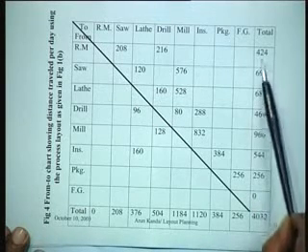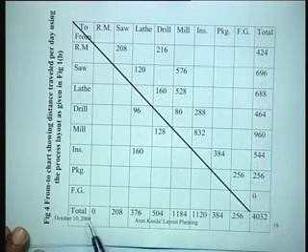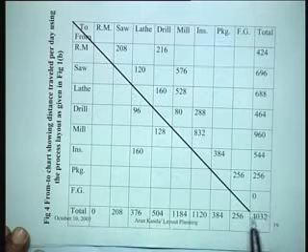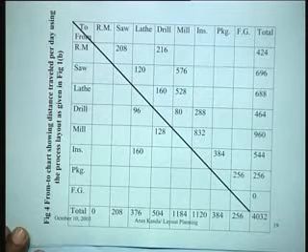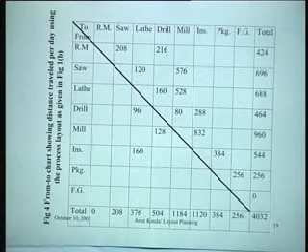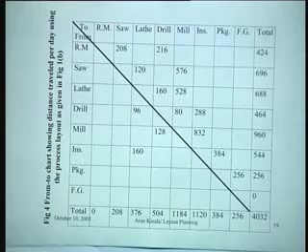If you sum up these values, this column or this row, the total value is 4032. So it shows that the process layout which we are at the moment investigating has a total material handling effort of 4032. This is a significant development, because what have we done?